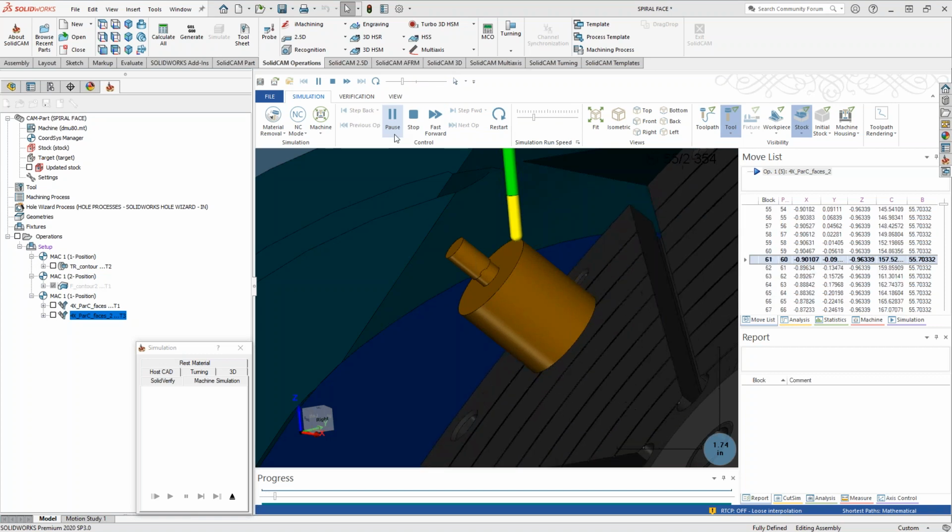And if I just run this slowly, the tool is at 45 degrees, but it's still generating 4th axis code. This is a full 5-axis machine, but just to really simplify the programming, I just said the Z-axis is still the rotary, but the whole table is at 45 degrees. Now the tool just comes through. Basically what we're doing here is turning our 5-axis mill into a lathe. Exactly.